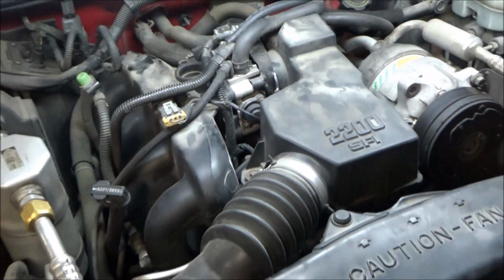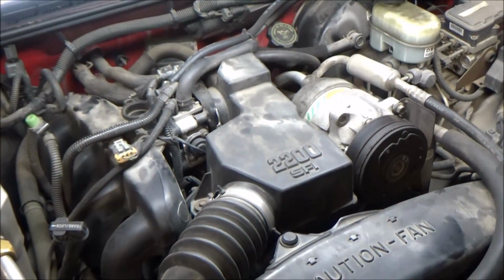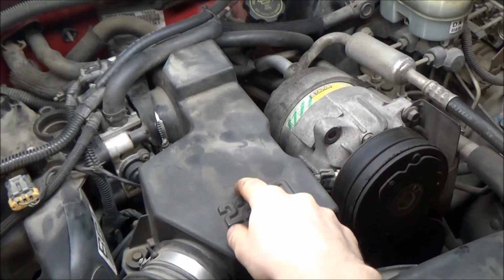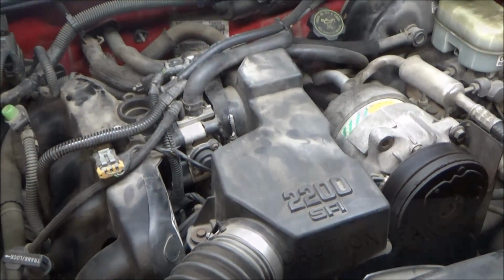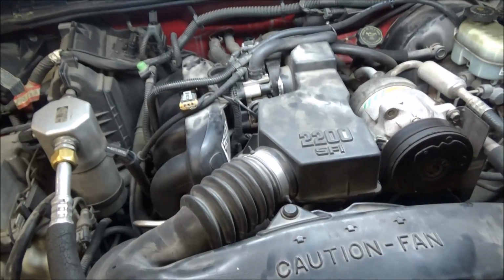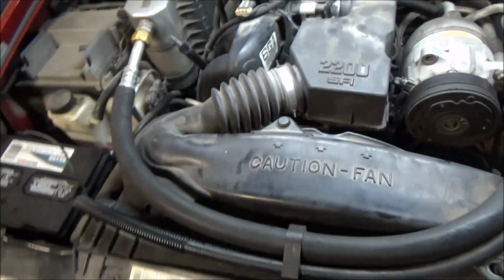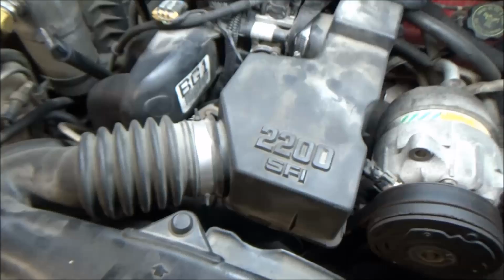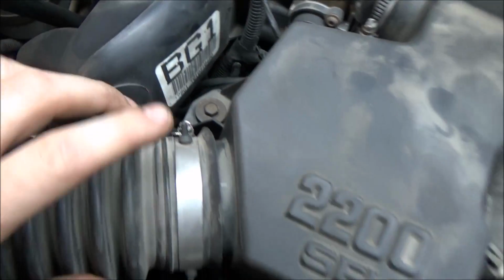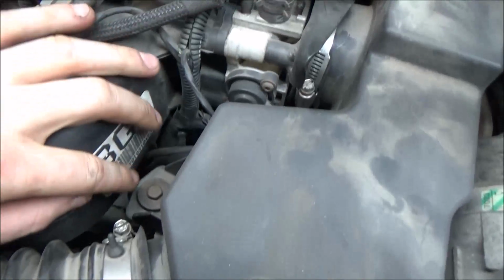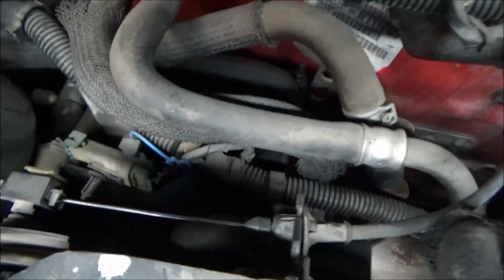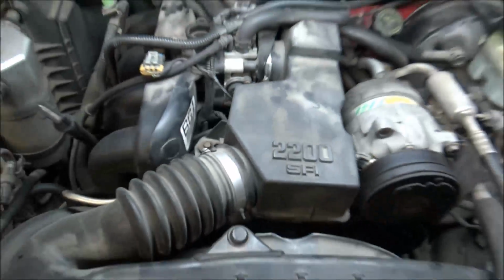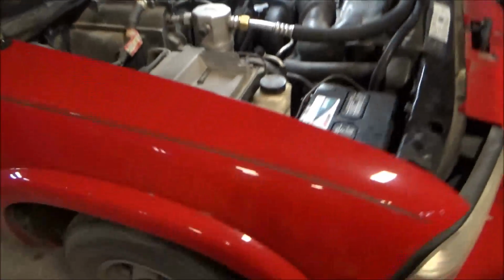So I think the next step to get to this throttle position sensor is to quickly get this air box out of the way, and then we can access the connector directly and perform some testing there. To remove this air box, guys, it's pretty simple. I'll give you a brief explanation, then I'll show you how to do it on camera. We have a hose clamp right here, just holding this hose onto this air box unit. We have one 10mm fastener here that I'm pointing to. We have a smaller hose that comes into the back of this unit. Let me see if I can get you a good angle on that.